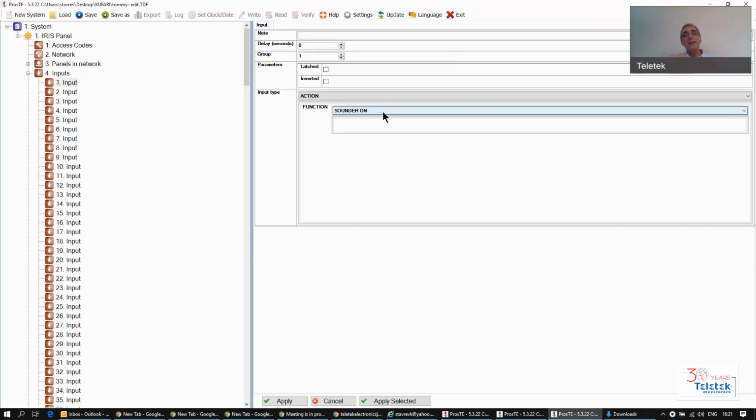This is when you want to activate some relays to send elevators down, open doors, fire escape doors, or other bells or whatever. You don't want to activate them before that. That's why I'm saying sounders on is probably one of the most used logical input that you can create. An input that monitors the sounders. In case that the sounders go on, then you can trigger different events in the system or different modules in the system.